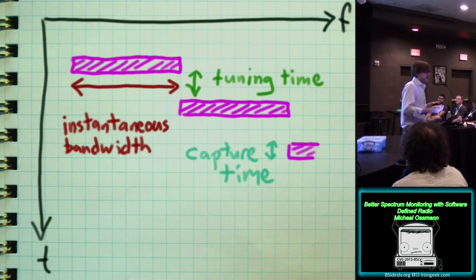But that's only part of the calibration problem. Having synchronized clocks means that their frequency measurements will all agree with each other, or their frequency configurations will all agree with each other very, very precisely. But there's also the problem of their power measurements. Calibrating the power level is another problem where you probably have to go through some active step to calibrate your equipment and see, oh, this one picks things up at this frequency 1 dB hotter than this other device does, so you have to come up with some calibration measurements and use that to normalize your data in some way. So you have to deal with calibration of power levels, time, and frequency. Those are excellent points.